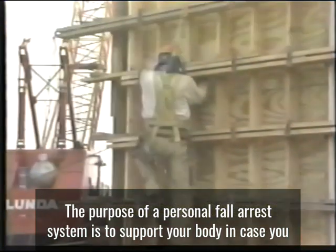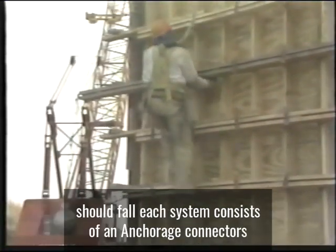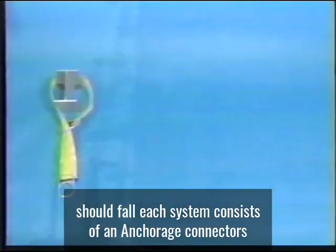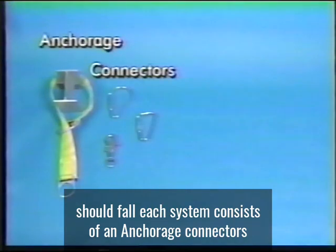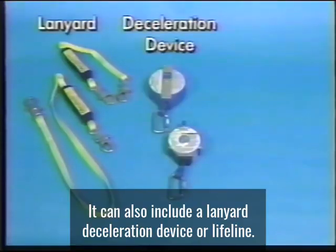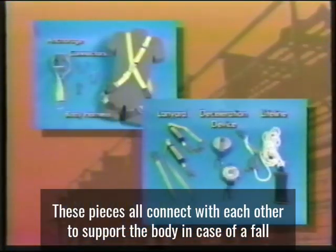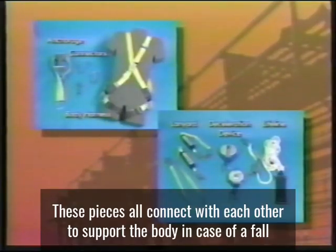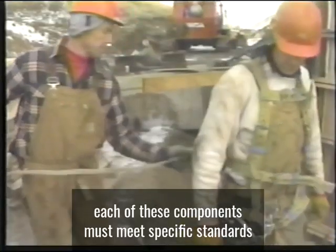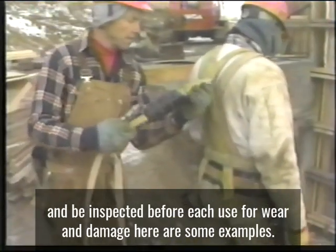The purpose of a personal fall arrest system is to support your body in case you should fall. Each system consists of an anchorage, connectors, and a harness. It can also include a lanyard, deceleration device, or lifeline. These pieces all connect with each other to support the body in case of a fall. Each of these components must meet specific standards and be inspected before each use for wear and damage.